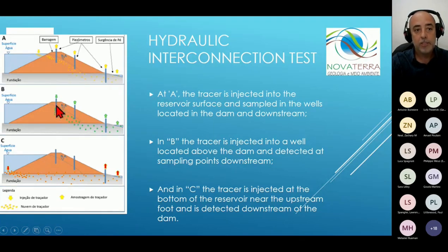Or we can inject in a monitoring well and detect the tracer in other downstream monitoring wells and in the outlet of the bottom drain of this dam.